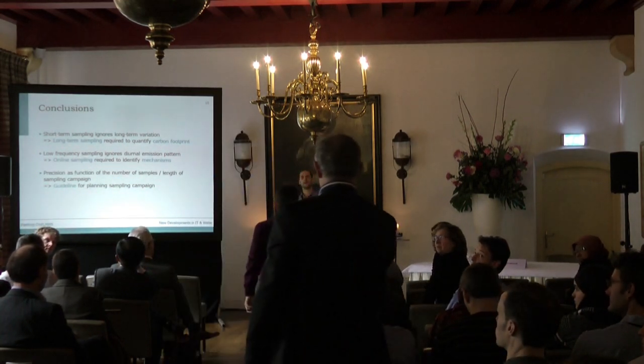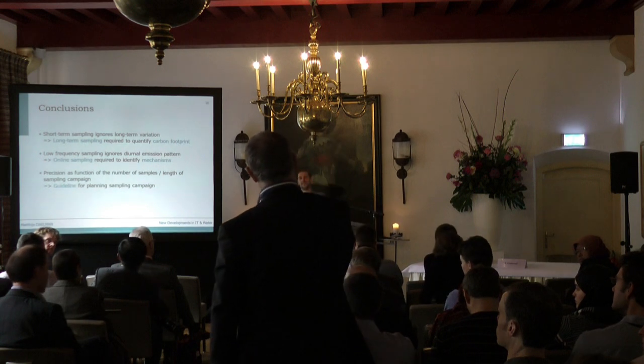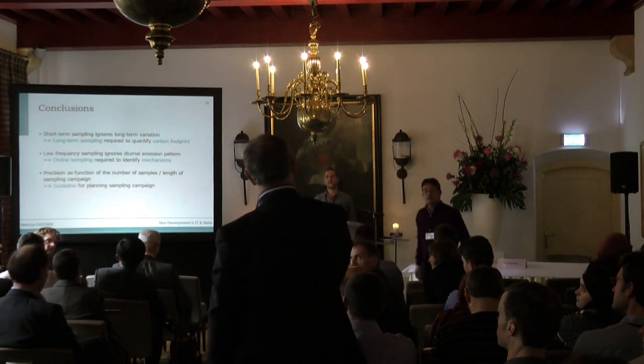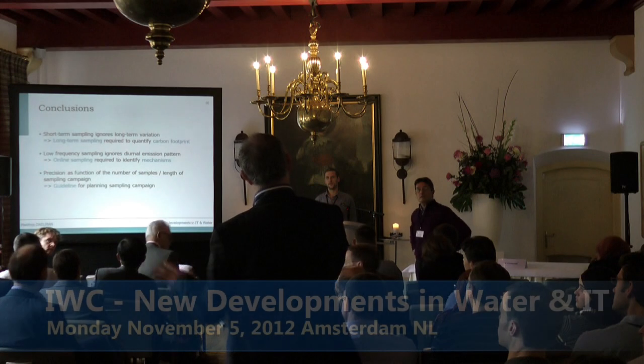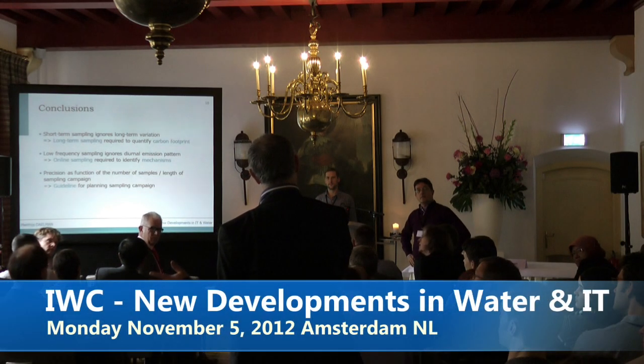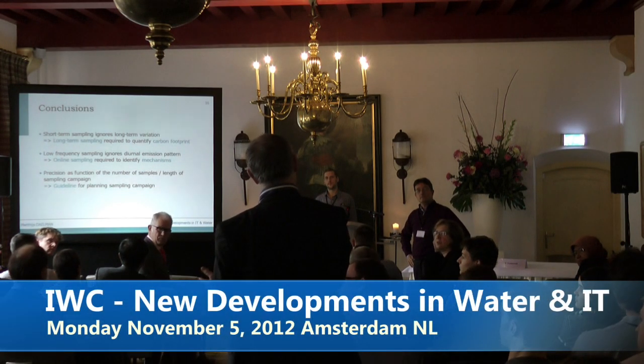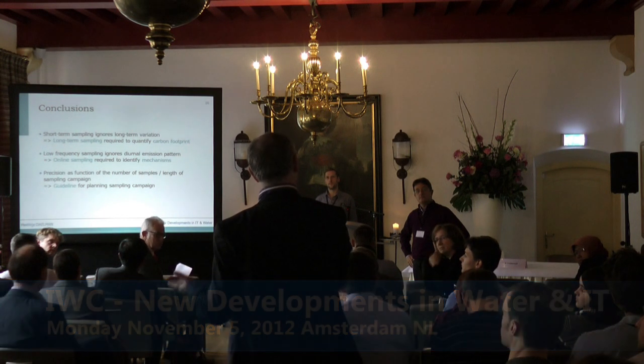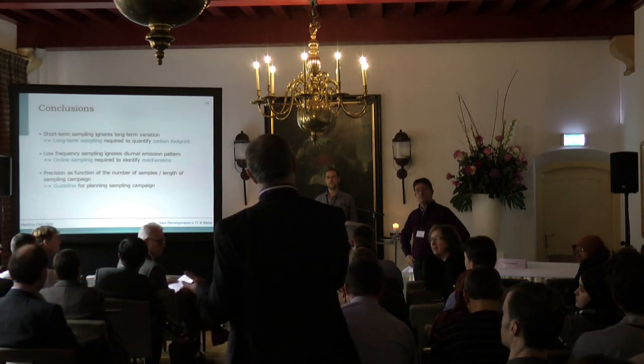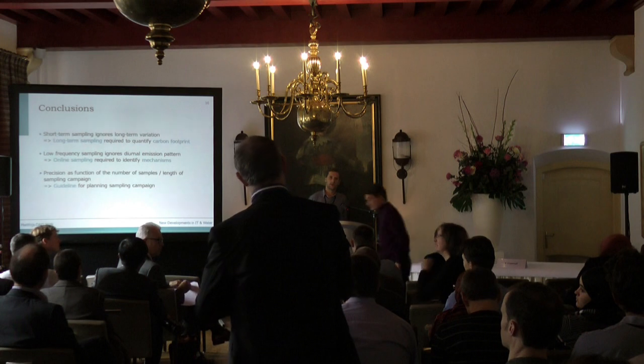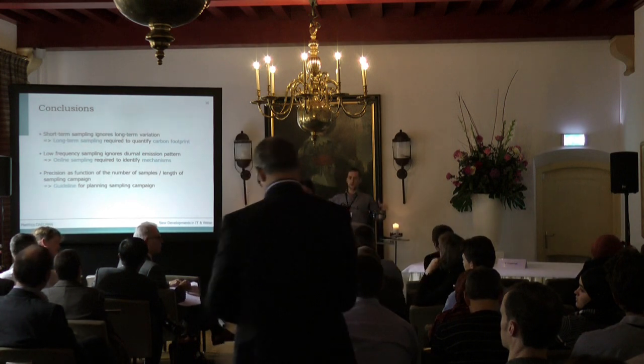Stefan Weijers, Waterschap de Dommel in the Netherlands. In some occasions you have a covered plant, then you can do off-gas analysis. Do you have any suggestions what to do if you don't have? What's a typical situation? Well, usually in that case, like a floating hood is used.